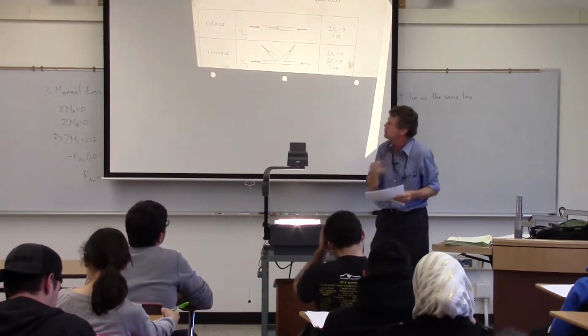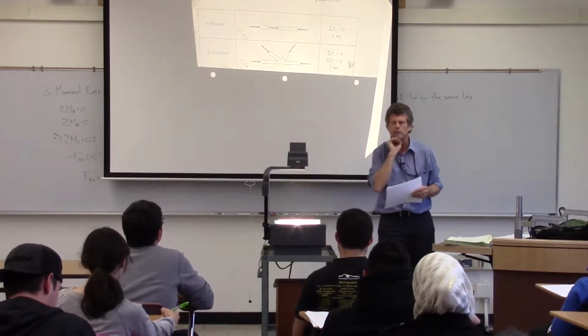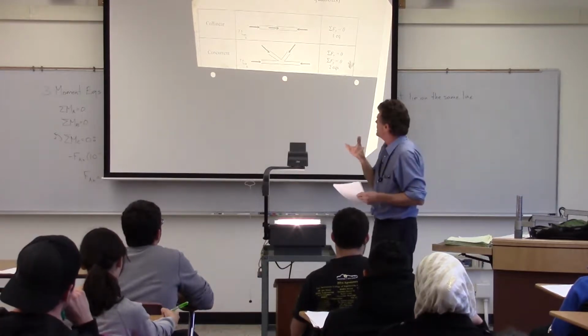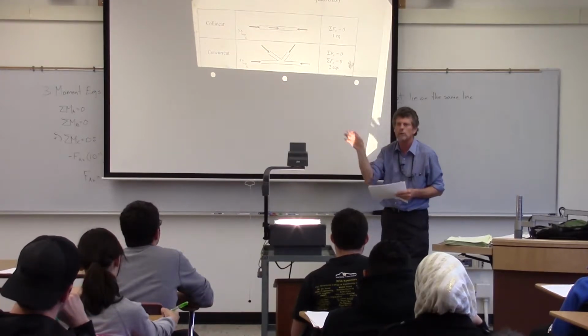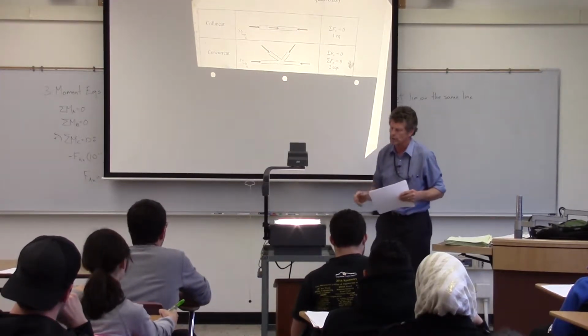And this will get important when we get into things like analyzing trusses. We're not going to be able to find 3 or 4 forces at a particular point. We're going to have to look for joints that only have 2 unknowns.